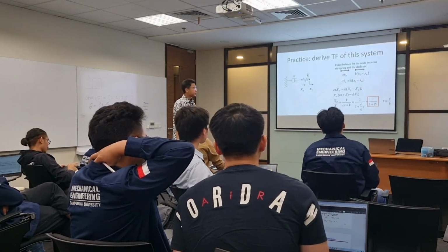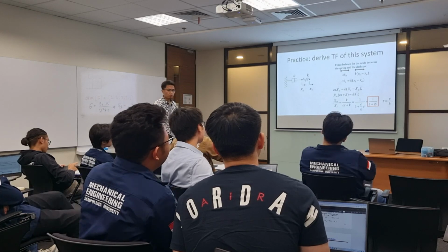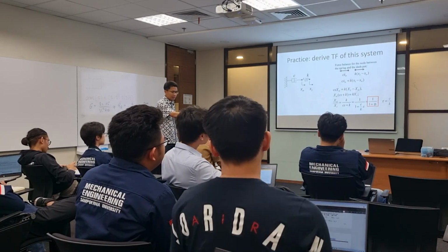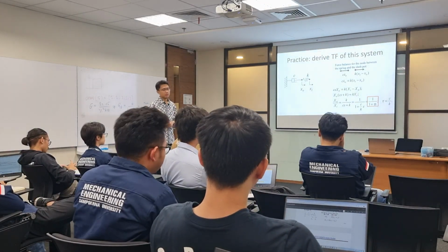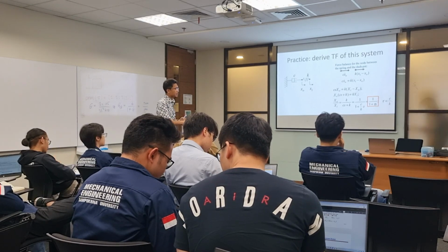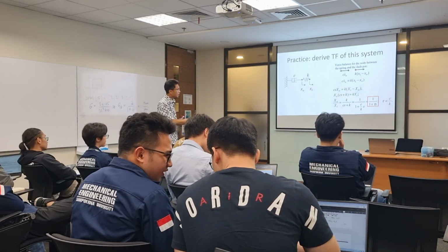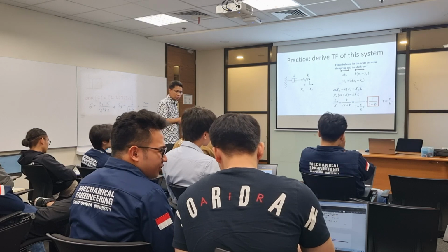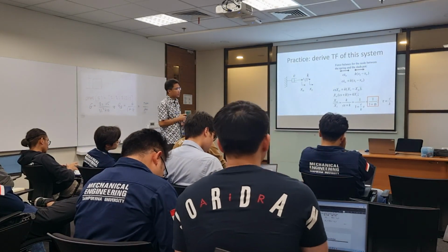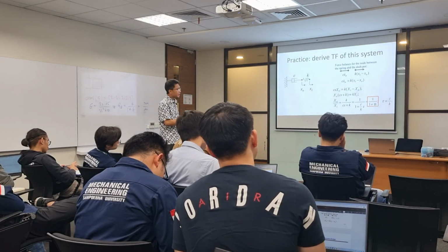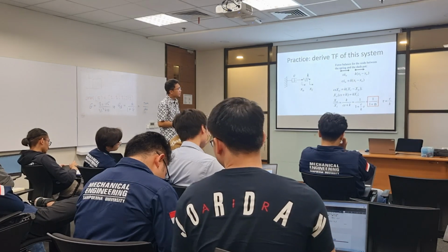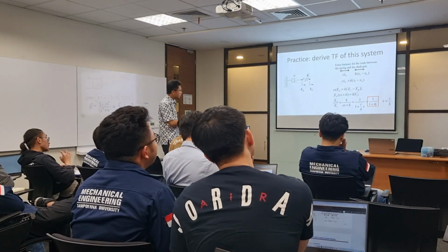In this case, the spring is being extended, we assume it is extended, so the force acting on this point is going to the right side. If it is being compressed, then the force will be going to the left. The damper force is always going to the left because of this condition.